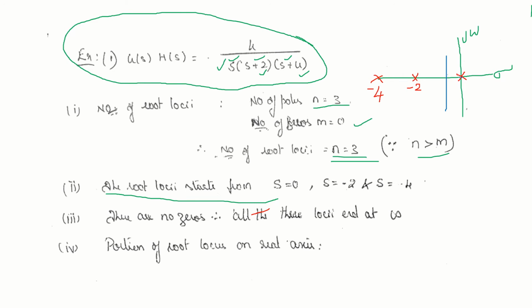So there is root locus on this part of the real axis. You go on moving this towards left to the right till it becomes odd only. Suppose if you keep your hand here and to the right, if you see there are two poles, even number of poles, there is no root locus here. Because you have to satisfy that 180-degree criteria. Now after that you come and keep your hand, there are three poles, odd number.